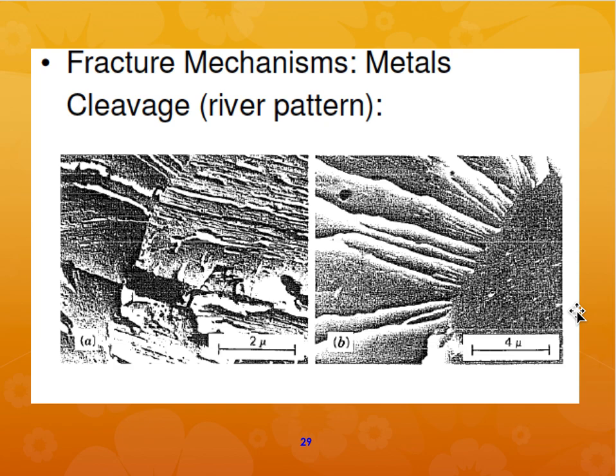So please understand that. If I give you a failure surface, please go to the textbook and see what kinds of surfaces are present. If you do that, you will find that near the fracture origination point, you will have a small flat area. And then it will go a certain distance in no time at all, and then boom, boom, boom, it will just go forward and break the material apart. Okay, so just wanted to tell you that.